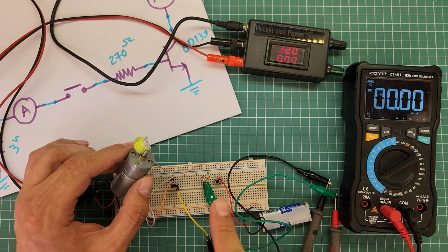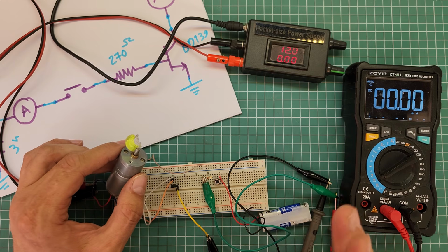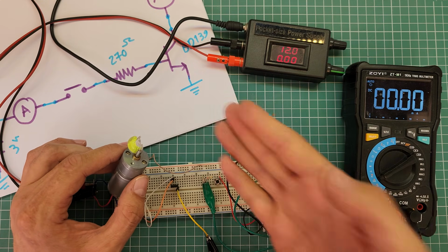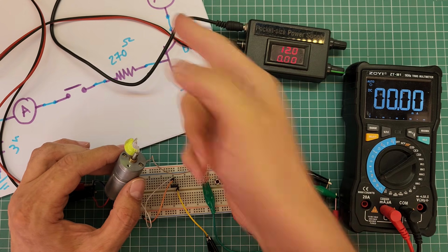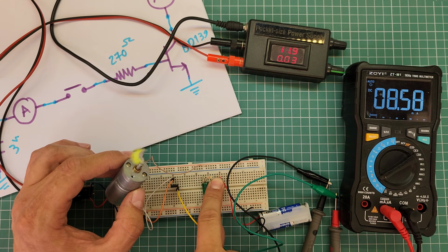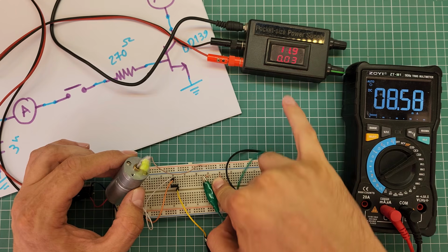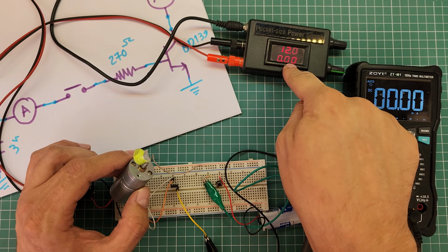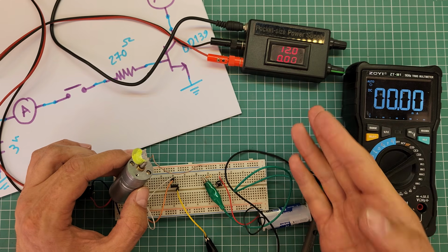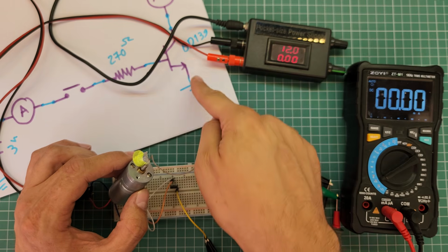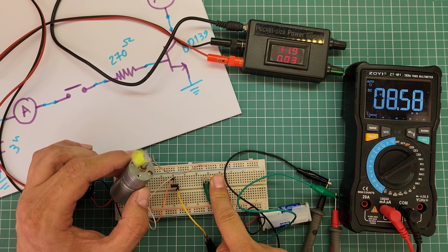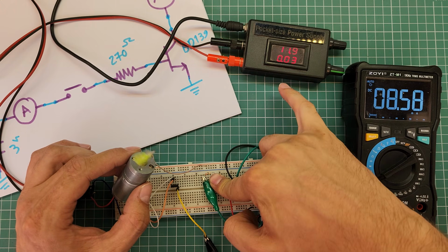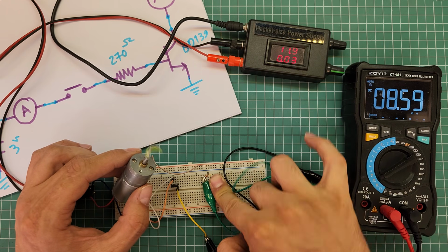When I press this tactile button, 3 volt will be applied to the base terminal of this transistor and it will turn this transistor on, and eventually this motor will be turned on. Look here and pay attention to these ampere meters. This ampere meter is this one, and this ampere meter is showing all current flowing to the collector of this transistor. Look here, this is 8 milliamp and this is about 30 milliamp.